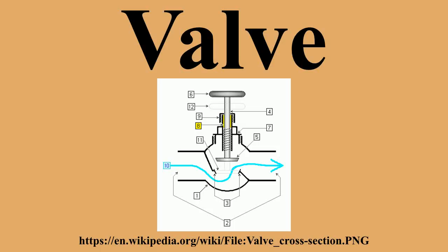The word is derived from the Latin valva, the moving part of a door, in turn from volvere, to turn, roll. The simplest, and very ancient, valve is simply a freely hinged flap which drops to obstruct fluid flow in one direction, but is pushed open by flow in the opposite direction. This is called a check valve, as it prevents or checks the flow in one direction.